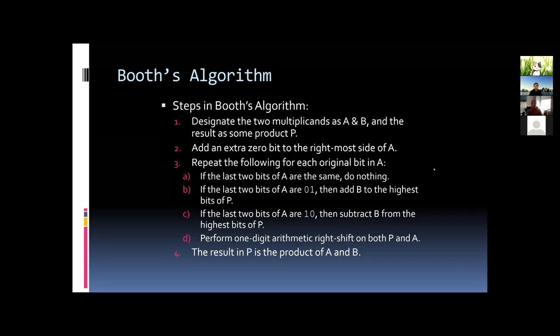Okay, sorry about that. So essentially the idea is when there are tons of zeros in multiplication, they don't do anything. So when I had a long sequence of zeros, I really care about the first one in this sequence. That one would force me to add B to the product, but nothing else is needed. If I had a lot of ones and then a 0 at the end, it means I need to convert it into all ones minus X. It means I need to subtract. That's the whole basic principle.